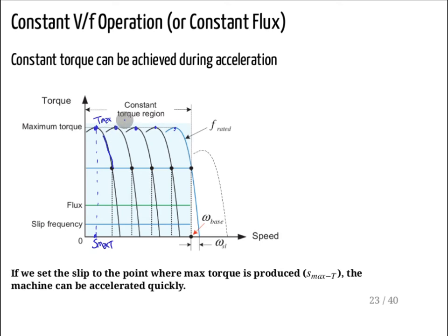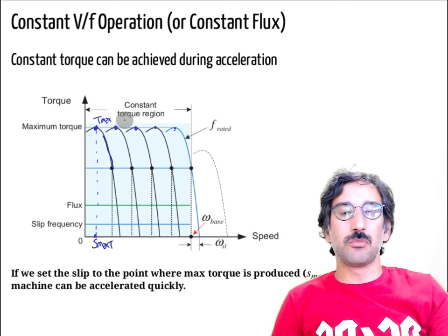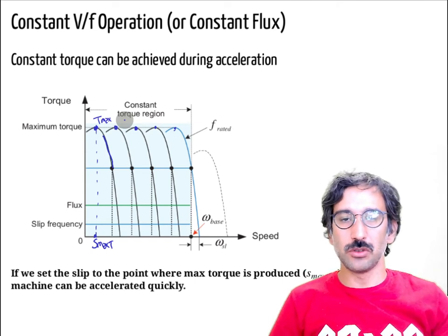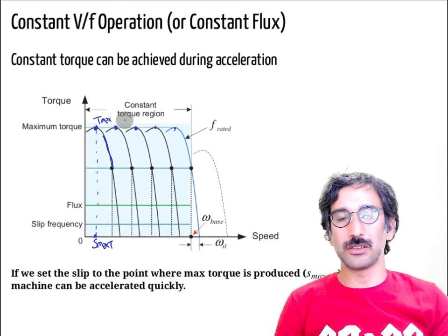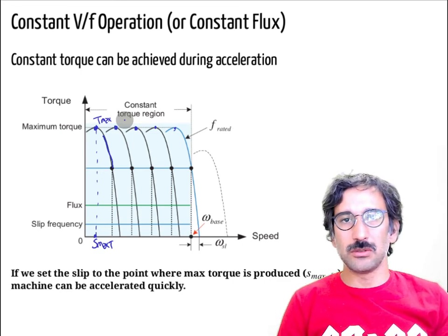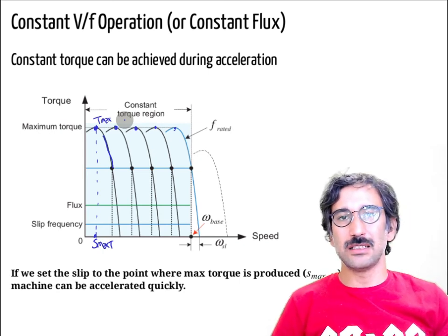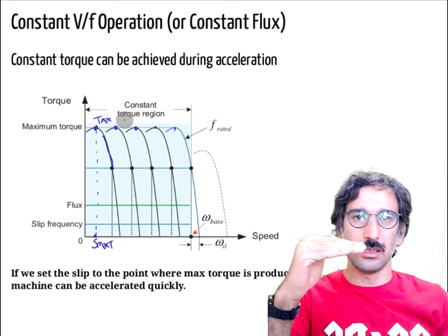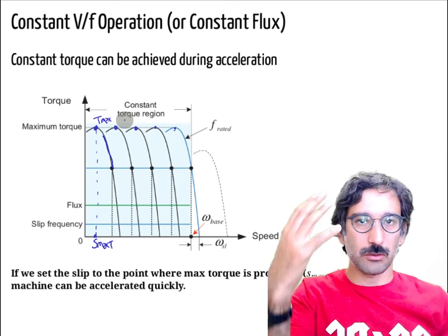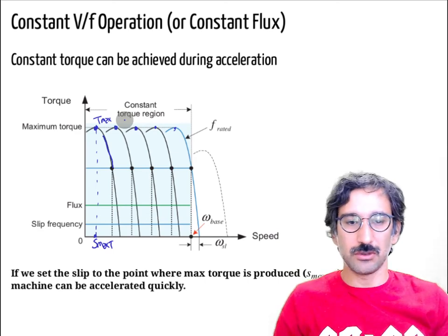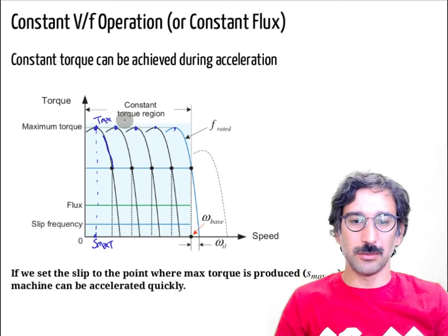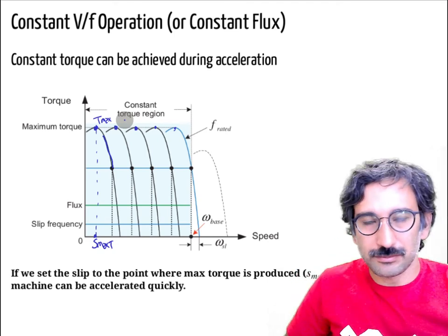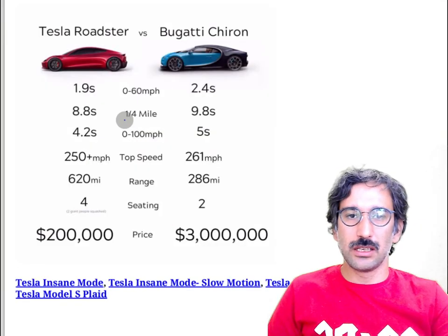Okay, probably that generates more power than the rated operation. So that kind of operation can be tolerated a couple of minutes according to the design of the electrical motor, but you don't want to run this motor continuously at the maximum torque point. But that is the advantage of electrical machines. Although there's some rated power, rated torque, there's also some maximum power, maximum torque, which it can give for short amounts of time. Okay, you can overload your machine for short amounts of time, and actually that is what electric cars are using quite a lot.